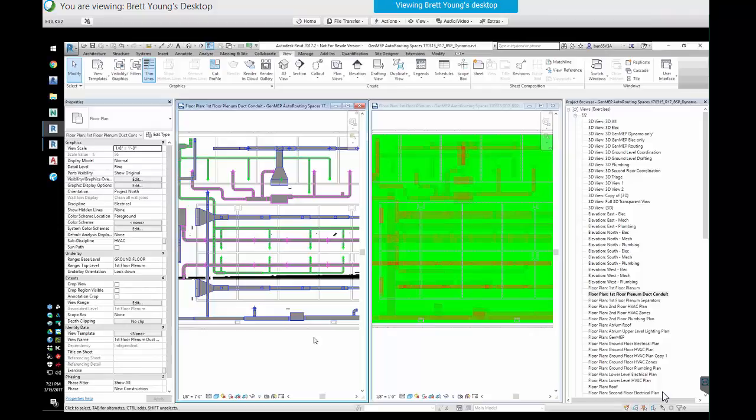The 300 projects we've looked at with a complexity of 30 at 50% DD means we need to change this now because it's going to be a problem when everyone gets their strut in there and their supports in there. We know that this is on the edge or even past the ability to coordinate. And you can do it early, when there's time to change some of that area, as opposed to at the end when you have to really spend a lot of money to fix that problem. That's my favorite part, is early fixes of not having enough space, or we can give space up.